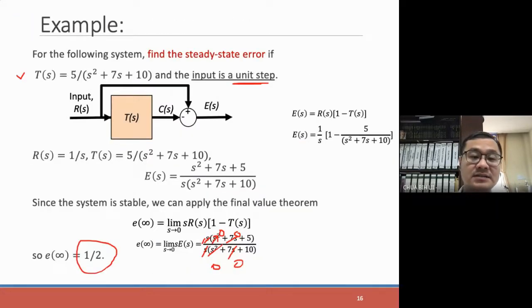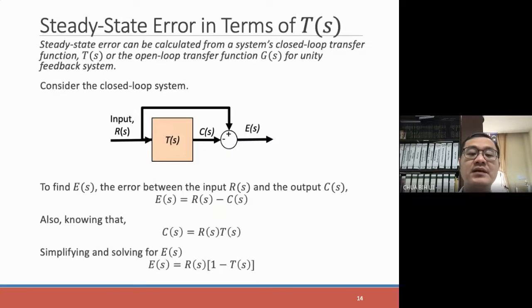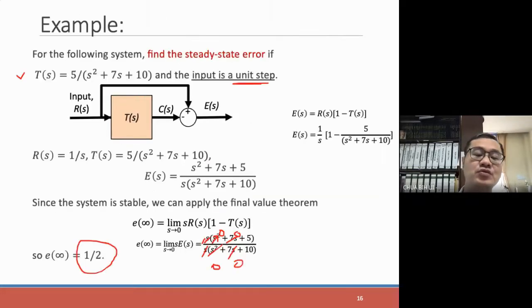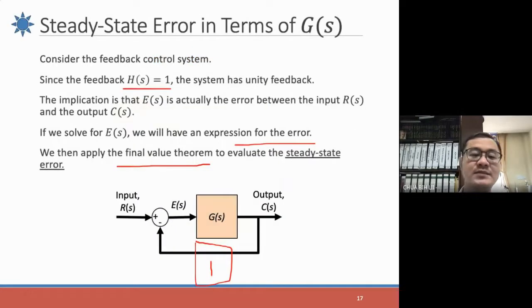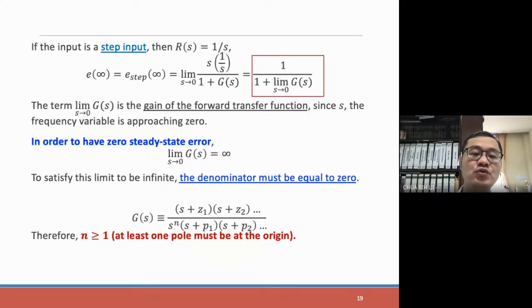Previously, this form of final value theorem is applicable when the transfer block diagram looks in this form. There is a slight difference in terms of derivations, but as you can see, the derivation is very straightforward. You just have to derive accordingly and get the final value theorem. So once we have the final value theorem, we will again start to evaluate.